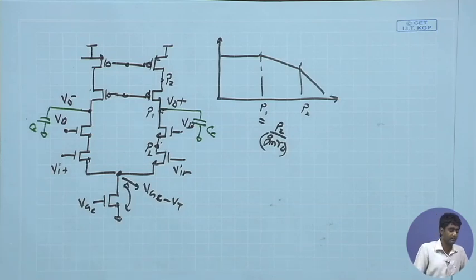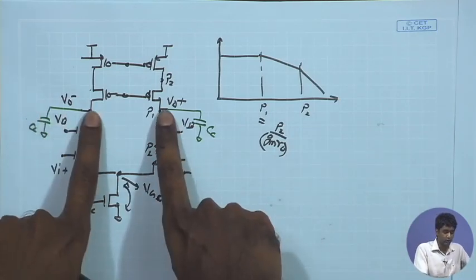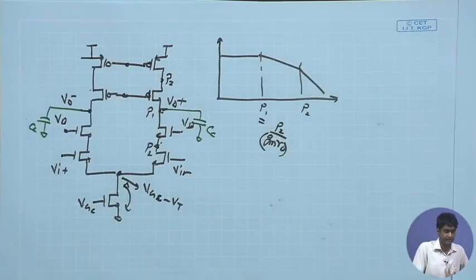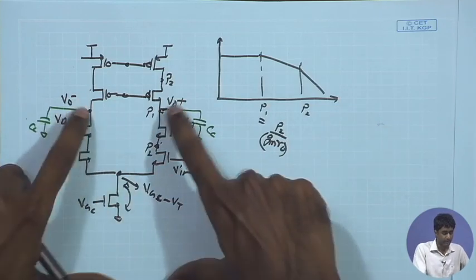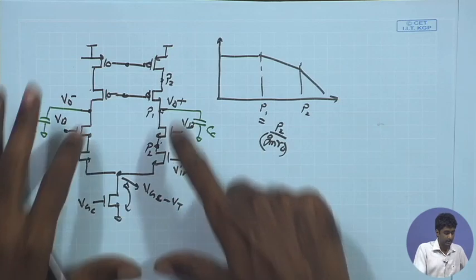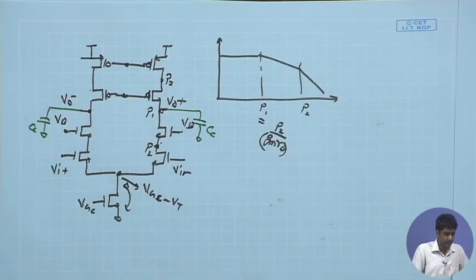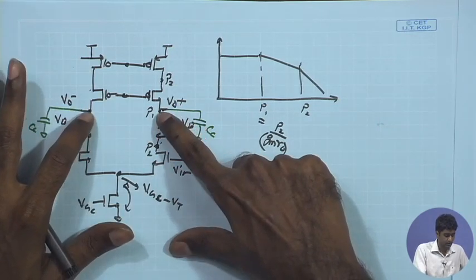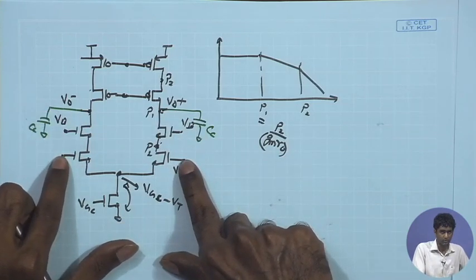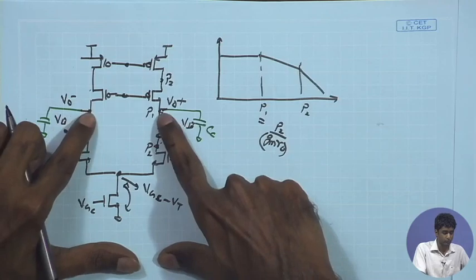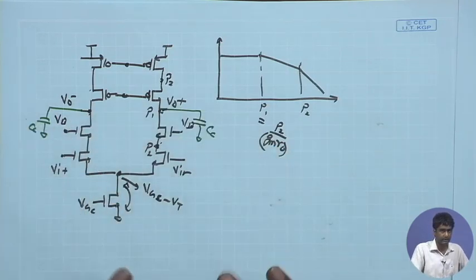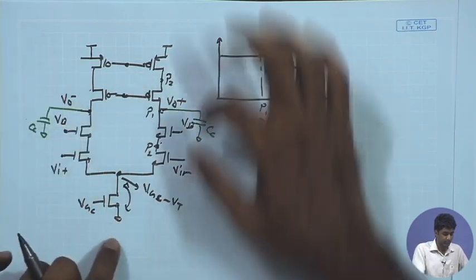In our example, we have stated that the output DC common mode is determined by common mode feedback if it is a fully differential operation, and with the help of that we are fixing the input common mode level. If we do that here, we will be pushing the input common mode DC level, or input bias point, close to the output DC level.